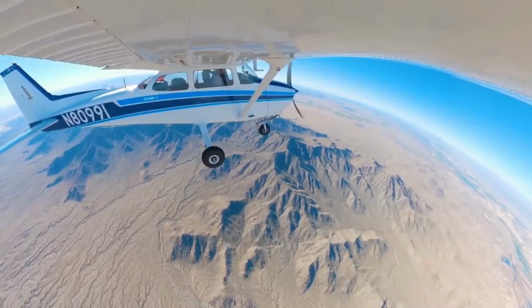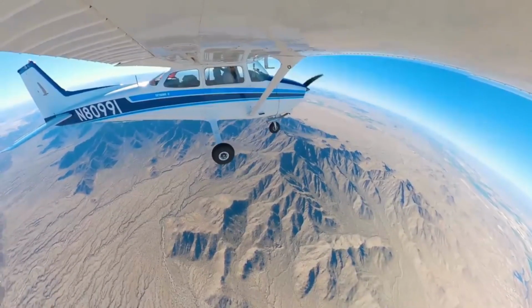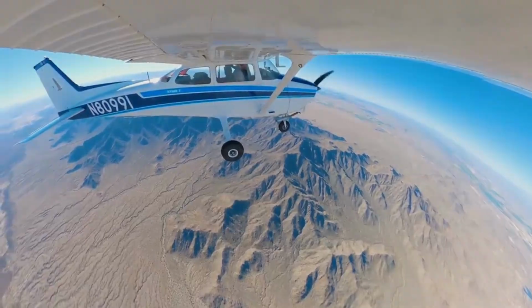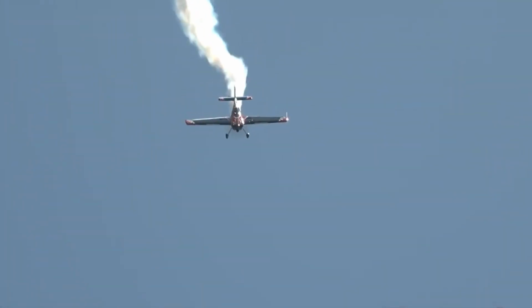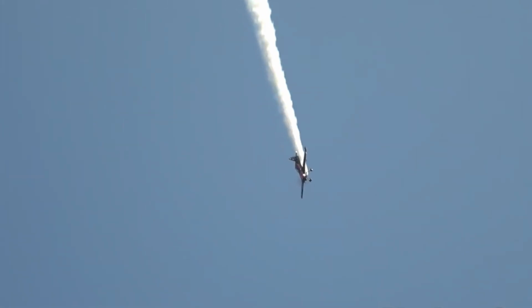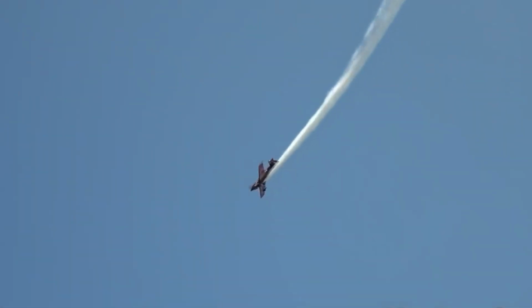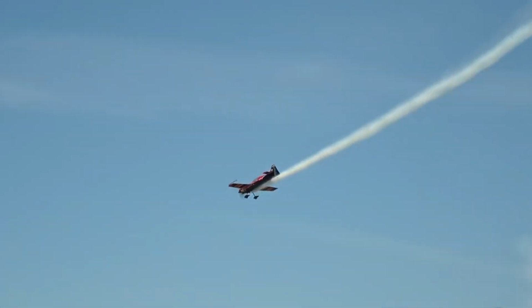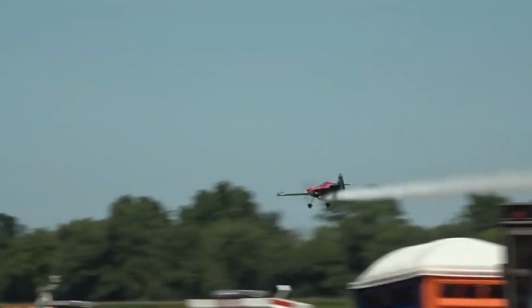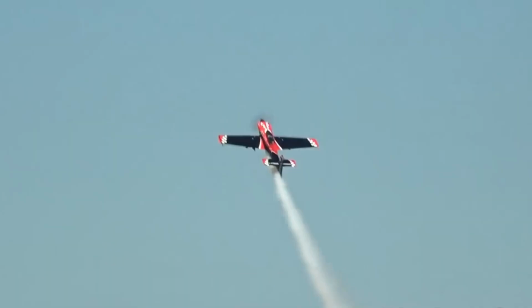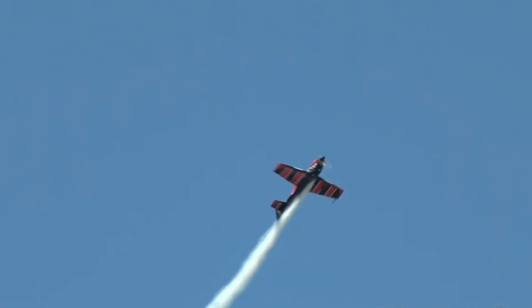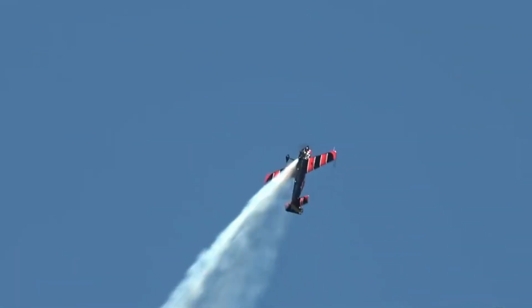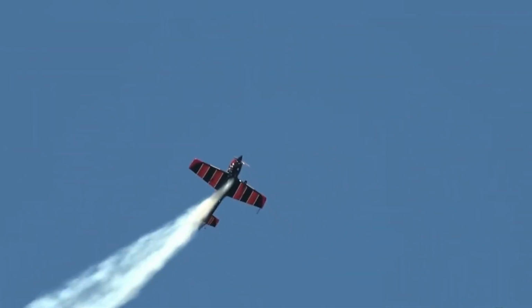The velocities of the layers increase as the distance from the surface increases until free stream velocity is reached, but all are affected by the free stream. The total distance between the skin surface and where free stream velocity is reached is called the boundary layer. At subsonic levels, the cumulative layers are about the thickness of a playing card, yet their motion sliding over one another creates a drag force. This force retards motion due to the viscosity of the air and is called skin friction drag.